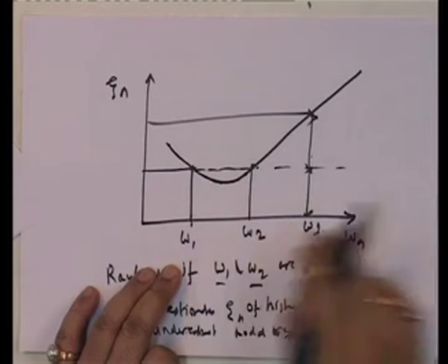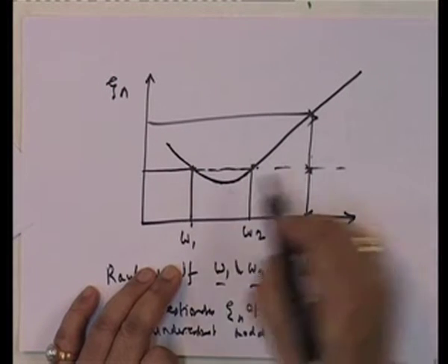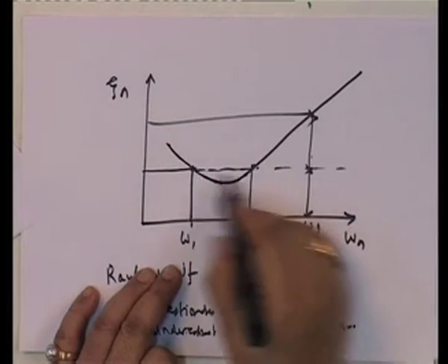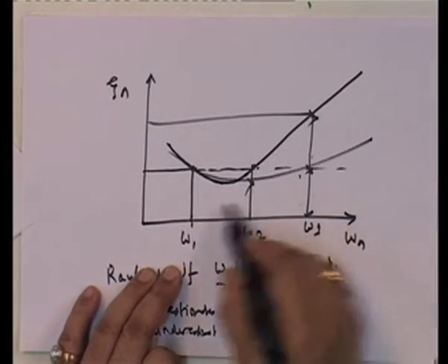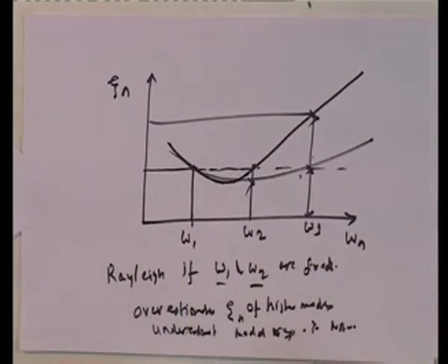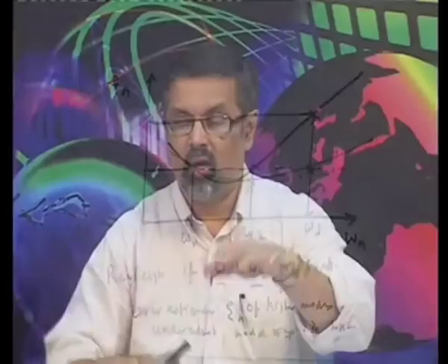in higher modes. So, in other words, in this process, what are we doing? If we do this, now there is another option. The other option is instead of omega 2, you do some other omega n. But then what happens is, if you fix this and you fix this, all that happens is that it underestimates the middle ones and overestimates the higher ones. Okay. So, you may say that look, I am underestimating a few, overestimating a few, which is why in a way Rayleigh damping has been used for so long.